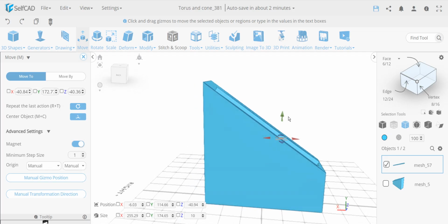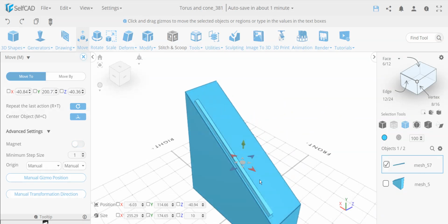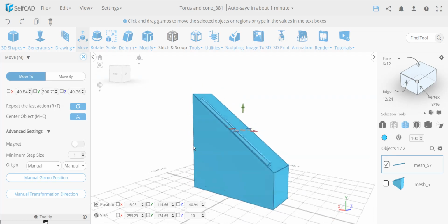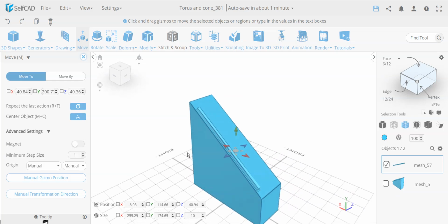You can see the y-axis is still aligned, everything is still the same, but it took the angle automatically. The magnet tool will take the angle from the thing it intersects, and it will basically align it to it. So this allowed me to, instead of using my measurement tool and figuring out exact angles, take the angle automatically, and it positioned it.